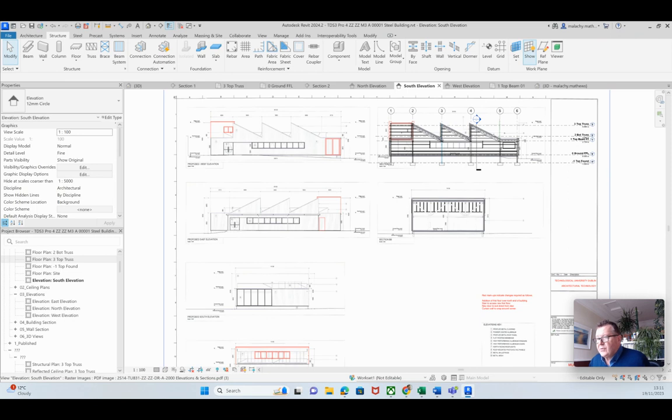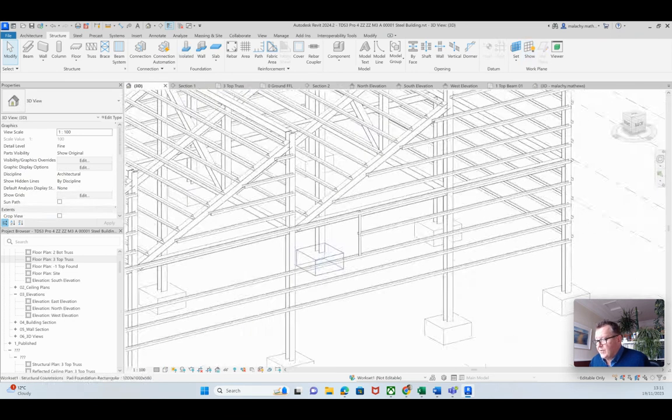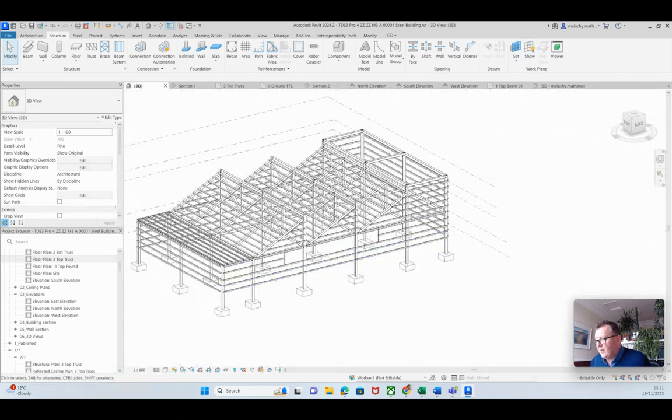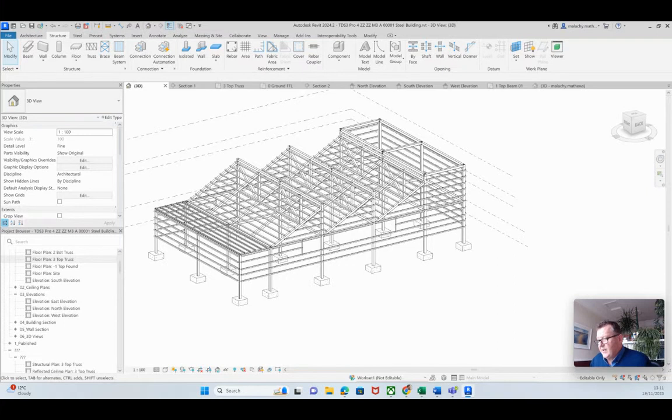Okay, so the final thing, if you've managed to follow along so far in terms of the structure, is that you're going to provide a roof platform here, roof platform there, and then you're going to frame out each of the openings by splitting the rails and putting in the vertical C channels or those integral Z purlins. Okay, that's it.